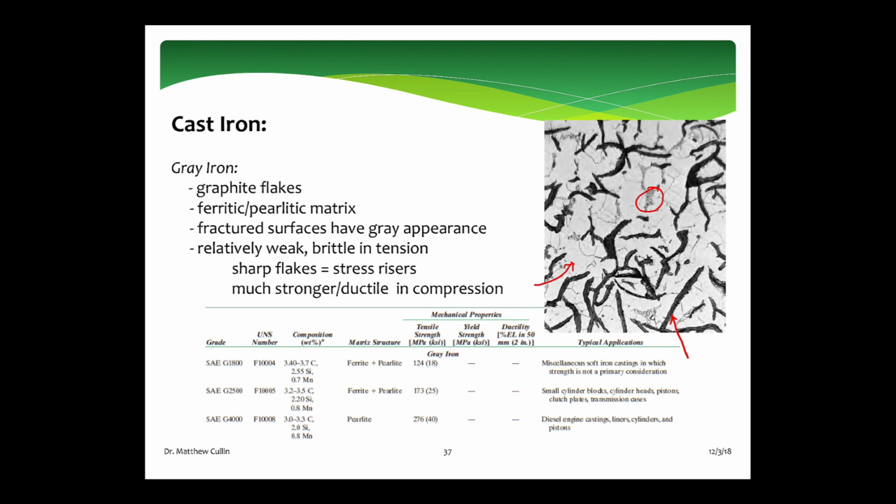These sharp graphite flakes are going to be stress risers, so it's not surprising that it's a relatively brittle material. We still use it a lot. We're just not going to use it necessarily in high stress applications.